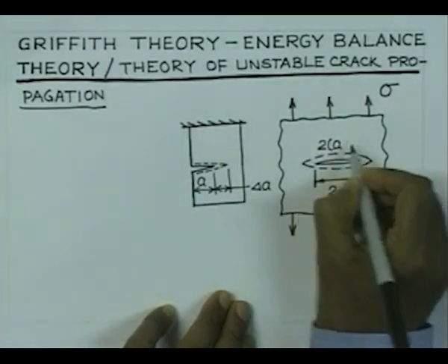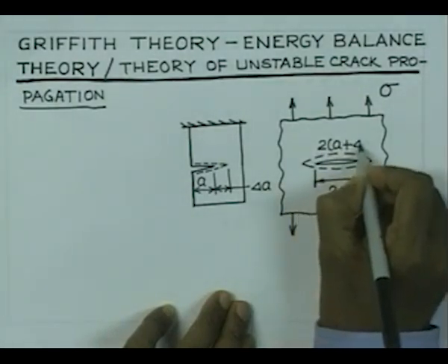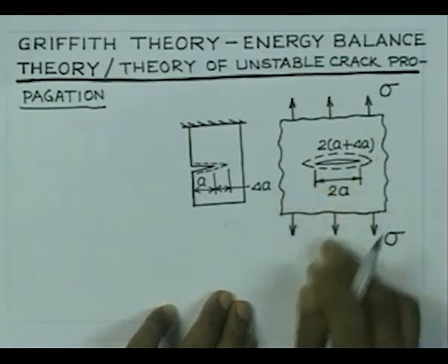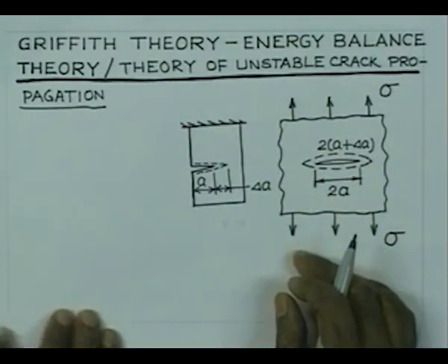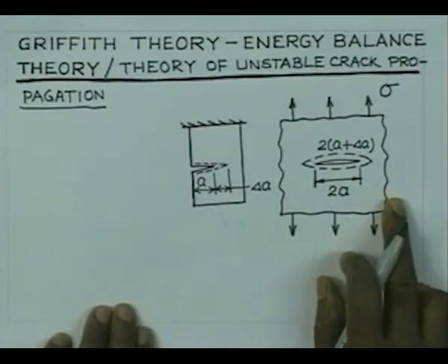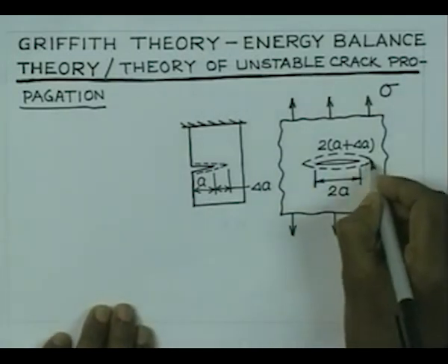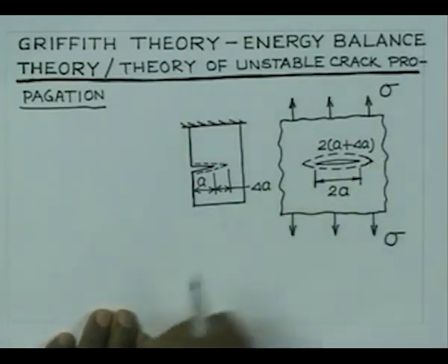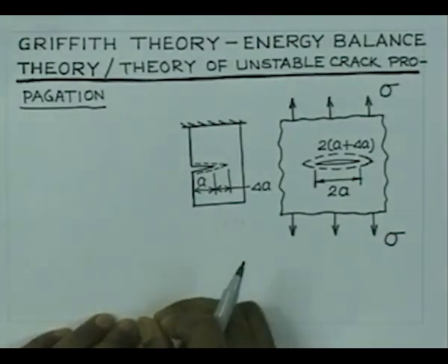So, that is the subject which was examined by Griffith, and he considered that this extension phenomenon of the crack can be treated like a thermodynamic process, and the condition for the extension can be obtained from the consideration of energy balance.